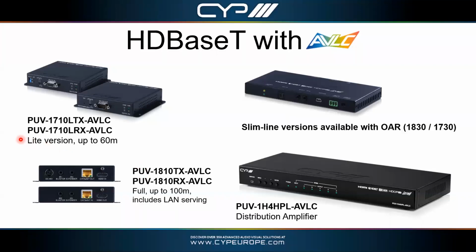When we talk about cable distances for the CAT cable and HDBaseT, we are referencing you sending a 1080p 60 hertz 444 8-bit signal. So, for example, for light versions, you might see other manufacturers that say up to 70 meters. And in fact, we could say the same thing, but you're not going to get 1080p at 70 meters.